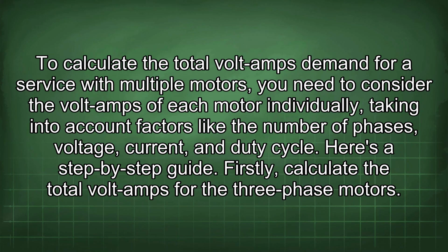To calculate the total volt-amps demand for a service with multiple motors, you need to consider the volt-amps of each motor individually, taking into account factors like the number of phases, voltage, current, and duty cycle. Here's a step-by-step guide. Firstly, calculate the total volt-amps for the three-phase motors.